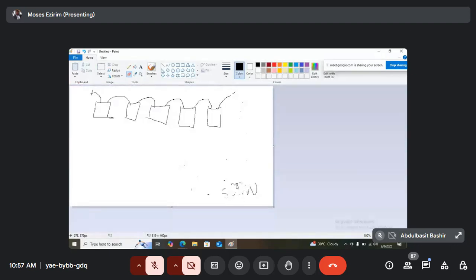So now let's see how to simulate this, if there is no bypass diode and this panel is shaded. All right. And remember, the voltage is still 20 and the current is still 5 amps. This is 20 V. Now remember, we are connecting in series. The same principle: connecting in series will increase the voltage, and the current will stay the same.